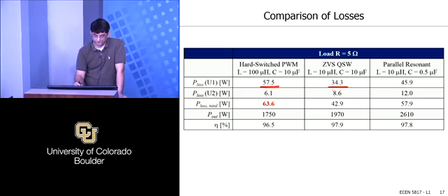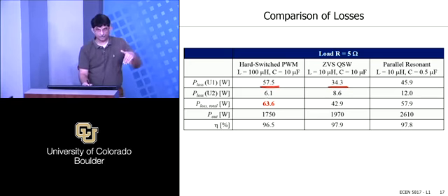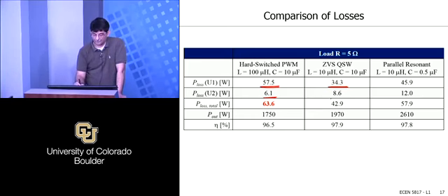All right. Let's look at the other device also, U2, which is the lower device, right? And that had even fewer losses previously, mostly in the diode, right? But those losses actually went up in this case when we did the quasi square wave.